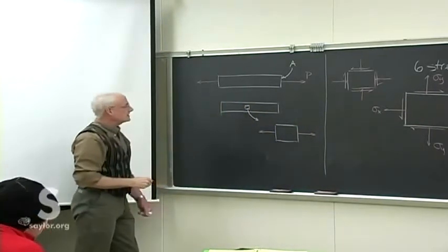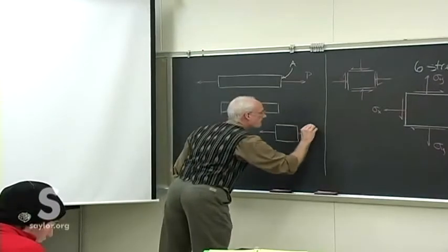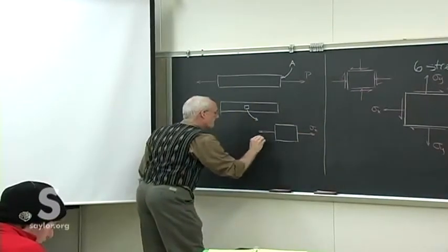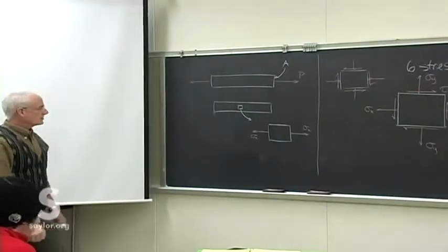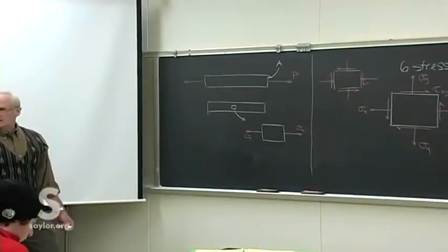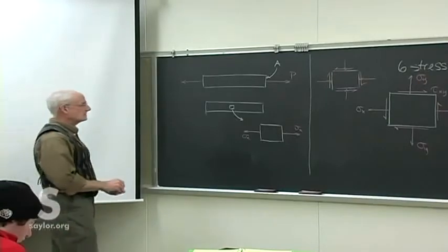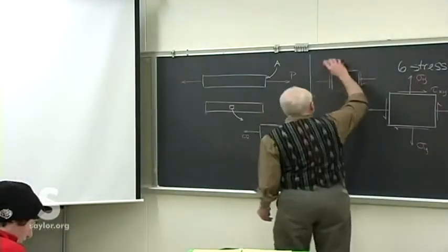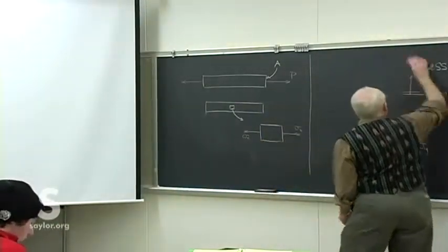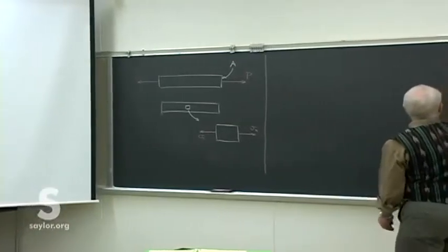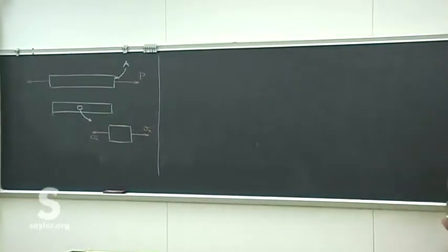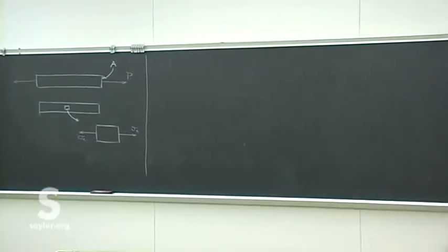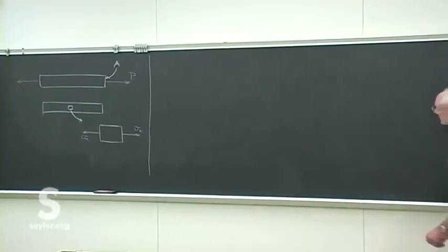For a simple axial load, all we're going to have is the normal stresses there. In that situation, there's no possibility of any shear stresses because I have no transverse component to the force, so I'm not going to have a transverse component to the stresses.